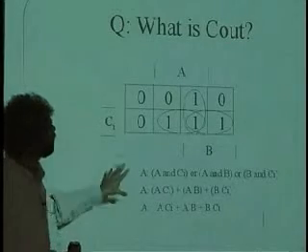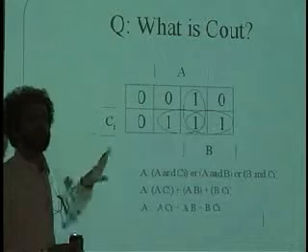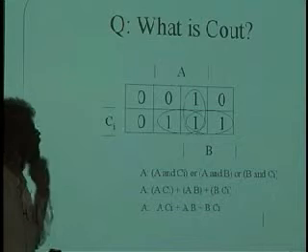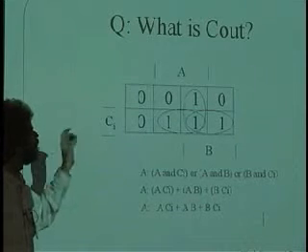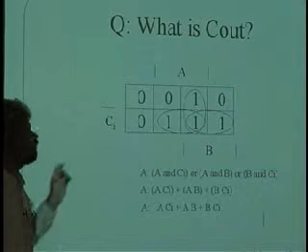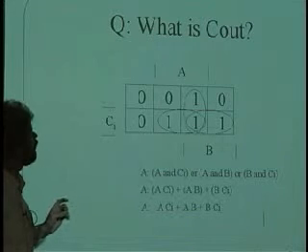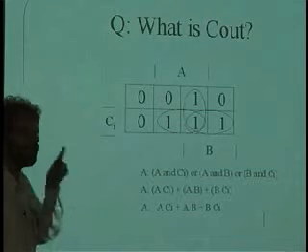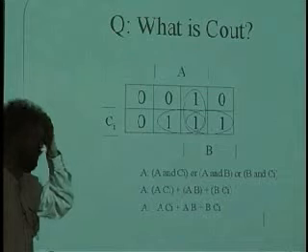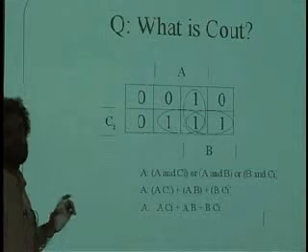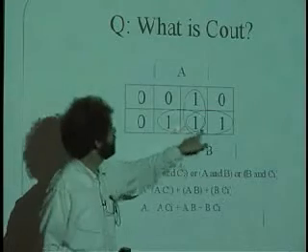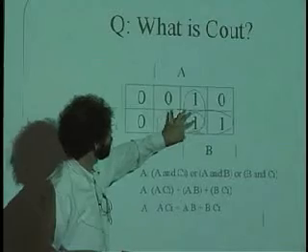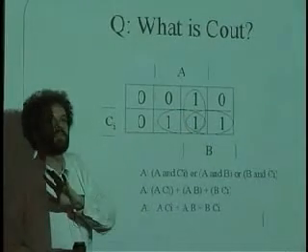Okay? What's wonderful is that this graphical technique allows you to simplify any sum of products form, anything where you have the OR of a bunch of ANDs, by sort of coalescing smaller circles into bigger ones. Now there's a few rules. The first rule is you can't make bigger circles whose size, whose number of ones they enclose, is not a power of 2. Now why is that? Well, when I merge these two ones by changing it from a circle that's as big as a 1 to a circle that has 2 things in it, I eliminate one variable.